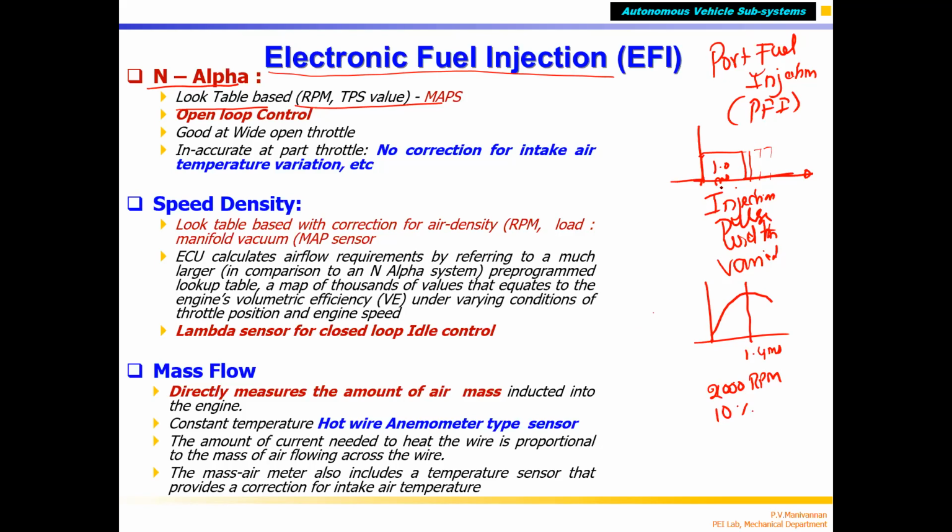How do you find this out? You vary the fuel injection by programming your ECU to vary the pulse given to the injector. This is a 12 volt pulse given to the fuel injector. We call it a pulse width modulated, PWM, pulse because I am varying the on time. The pulse on time is increased from a small value.